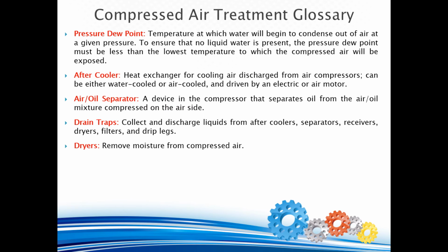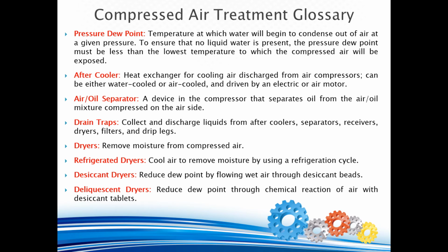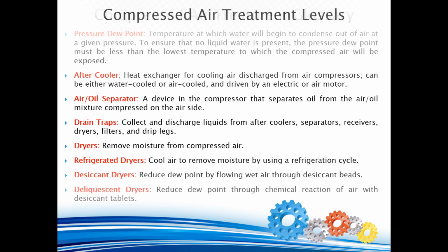Dryers. Remove moisture from compressed air. Refrigerated dryers cool air to remove moisture by using a refrigeration cycle. Desiccant dryers reduce dew point by flowing wet air through desiccant beads. Deliquescent dryers reduce dew point through chemical reaction of air with desiccant tablets.